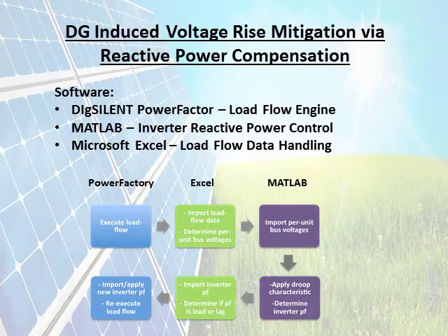The simulations were performed using 3 pieces of software. DIgSILENT PowerFactory was used as the load flow engine, MATLAB was used to implement the reactive power droop control for each inverter, and finally, Excel was used to handle the large amount of load flow data that had to be interfaced between PowerFactory and MATLAB.